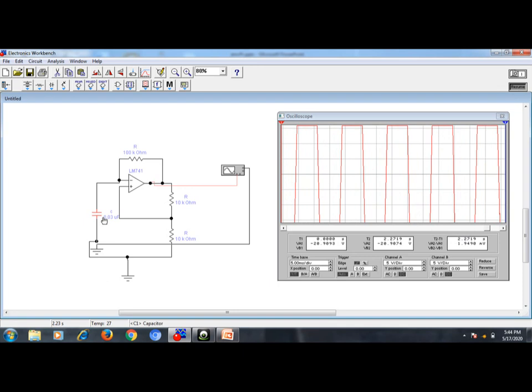That means as you increase the capacitor, there is a change in the time period. The experiment is to be repeated for different values of the capacitor, and you are able to get the square wave. Students, remember that you are calculating the theoretical frequency and the practical frequency. Both should be equal, then your practical is correct.